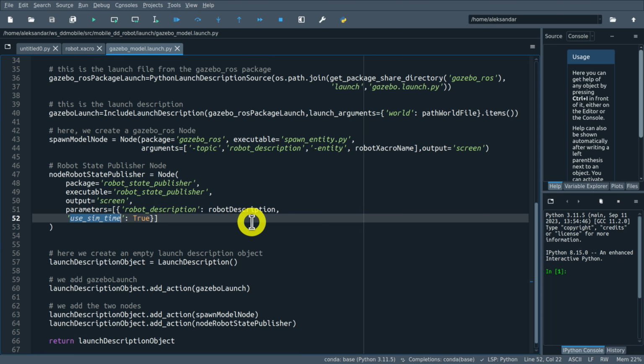Okay, so how to do that? Well, let's see. Our complete model depends on joint_state_publisher, robot_state_publisher, gazebo_ros, xacro, and rosbridge. So we need to include these dependencies. Let's simply include them. You can put them, for example, over here.